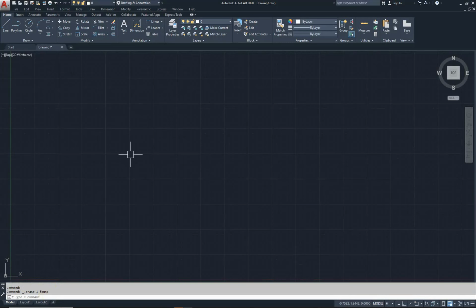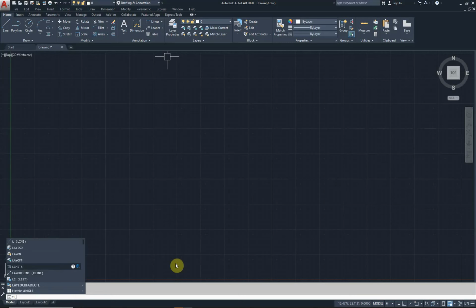In AutoCAD, if I want to activate any command, we can choose it from our menu bar, from our quick access toolbar, from our ribbons, or if we know the shortcut key, we can directly type it into AutoCAD. Like if I want to give the Line command, I just give the shortcut L. In AutoCAD, to activate any command through the keyboard, we need to hit Enter or Spacebar in most cases. And for some commands, we don't need anything like that.